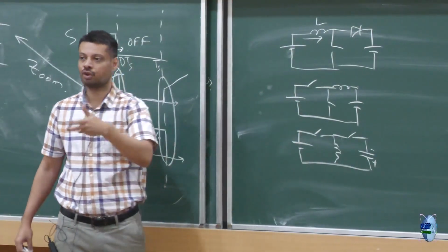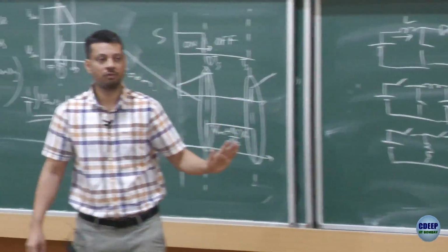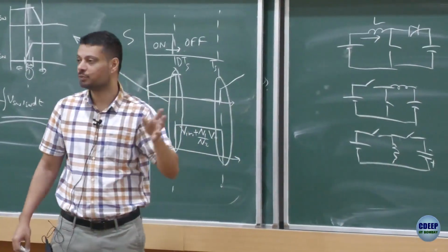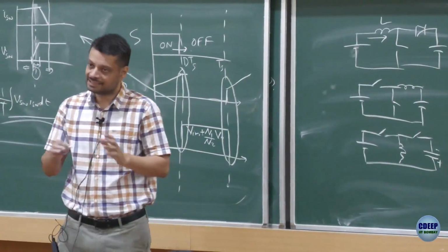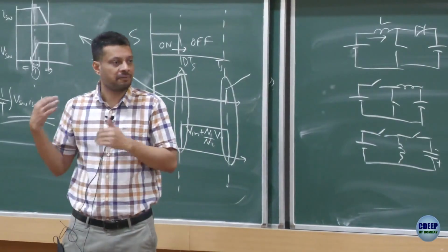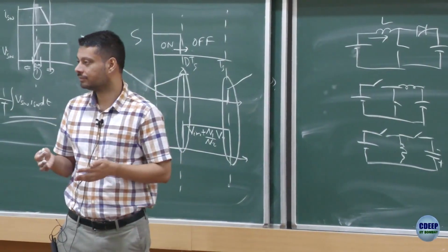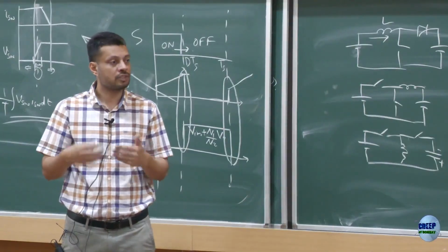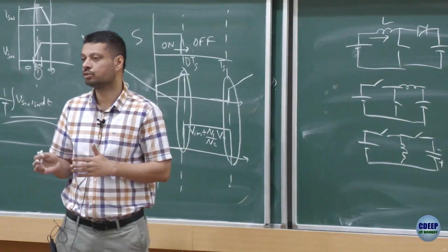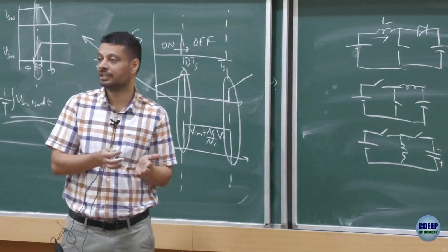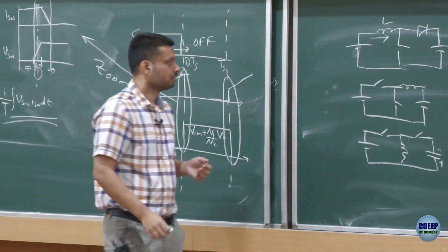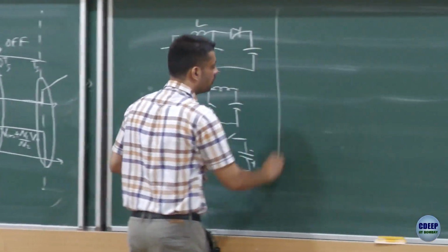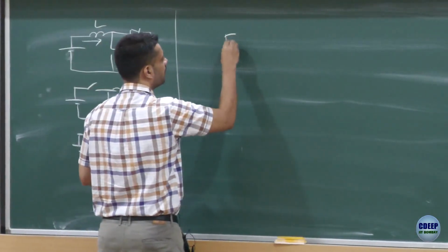So if your choice is that you always have to boost, you don't go with buck boost, you go with boost. And that's the same reason. If you remember, the flyback is like a buck boost circuit, right? If you always operate in boost, or you can always operate in buck, you should not use flyback then. You can use some other topology, right? So we move to something called a forward converter.